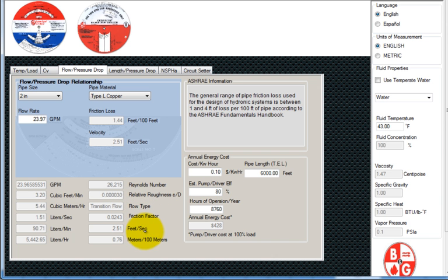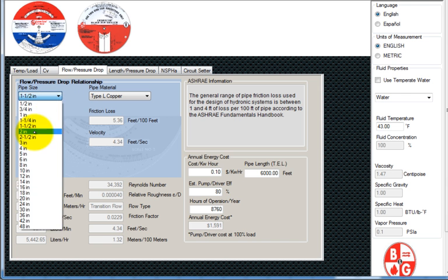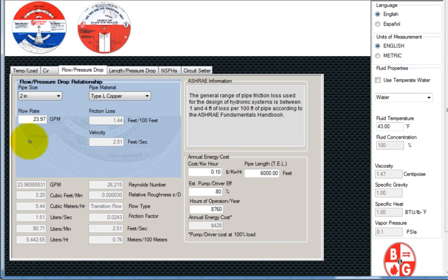There's the friction factor, feet per second, 2.5, etc. That's pretty good, foot per second. This would be a good choice. I think if you went with 1.5 inch, you're getting a little high on the friction in that. So typically you go a little higher. There you go. So let me jump back here.